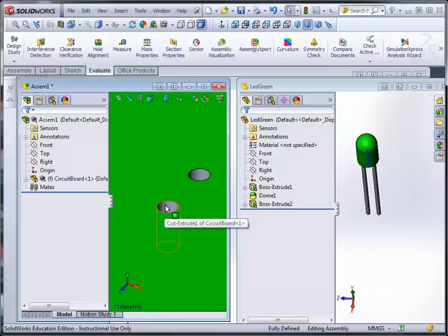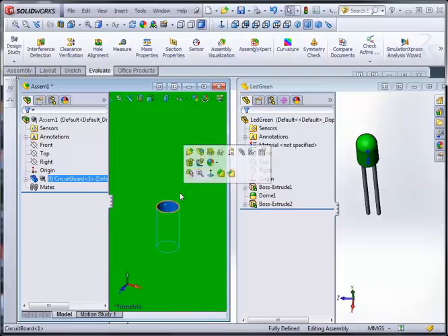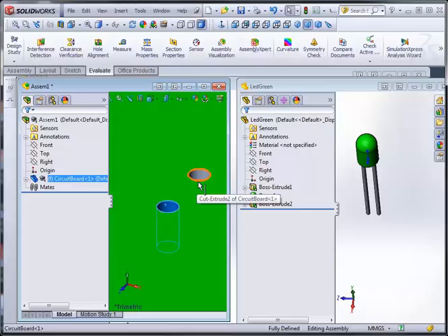As soon as the green square shows next to the mouse, which means you're hovering over a face, we will select that. Another symbol, a green line, represents that you're highlighting an edge. This is very useful at times if you want to figure out if your mouse is over an edge or a face, especially with smaller lines that you can't properly see and you might have to zoom in a lot for.